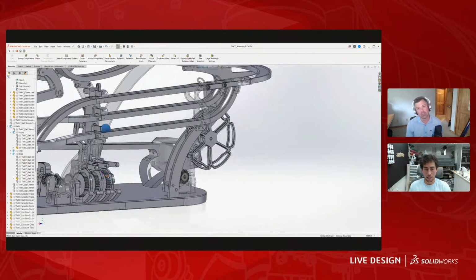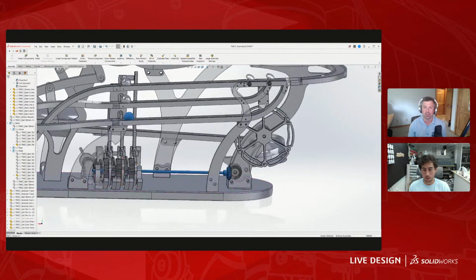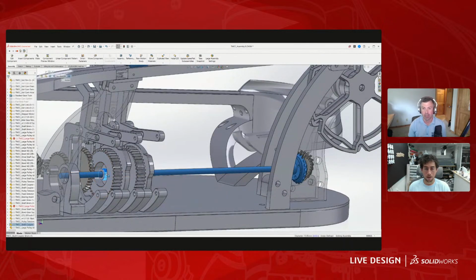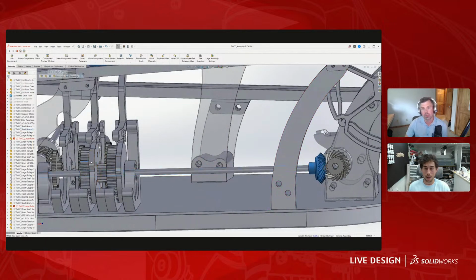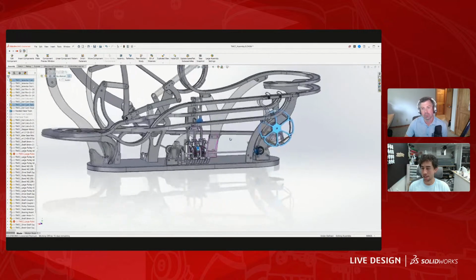And I knew that this wheel was rotating once an hour as well. So I connected them with the shaft, this bevel gear. So this gear, and it's going to be kind of hard to show you, but there's a coupler that is connected to this gear right here, which is connected to this shaft. So this gear and cam and this cam are rotating together.